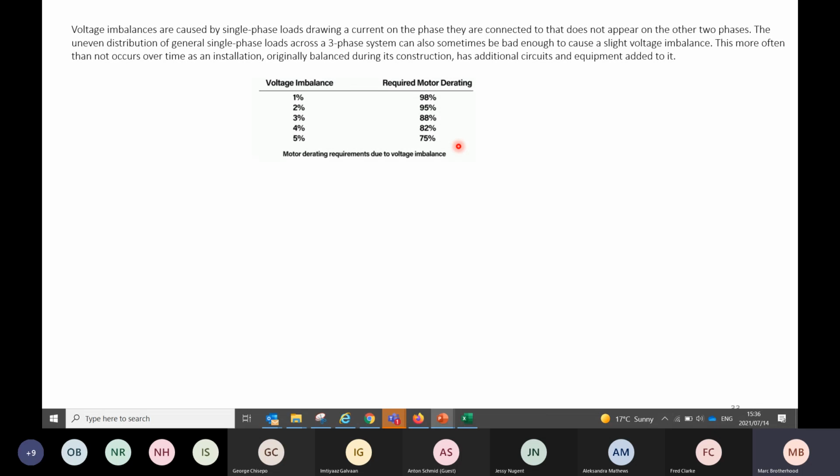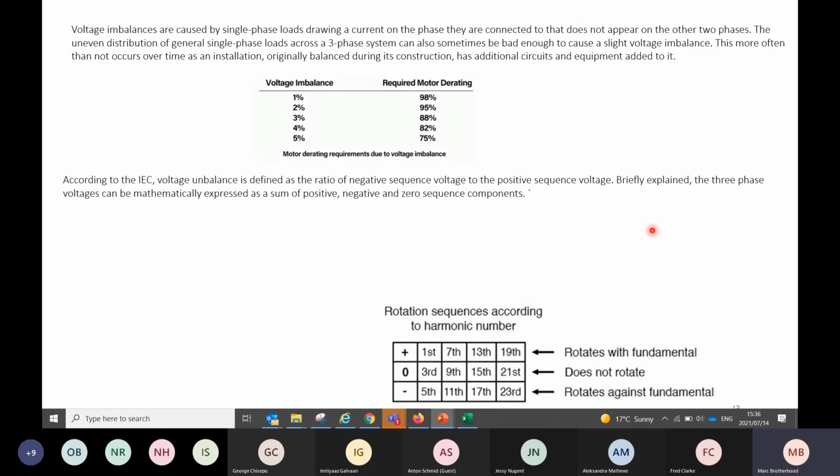The chiller keeps on tripping. Get the guy out there to look at the chiller. They can find nothing wrong. In the afternoon, the problem goes because the single phase loads get switched off and everything's back to normal. So this is just the effects it can have on, say, a chiller, or anything that rotates. A non-inverter chiller, by the way, standard compressors, or a chiller operating a pump, primarily the motor supplying the pump. So I'm going to have a huge water flow issue.